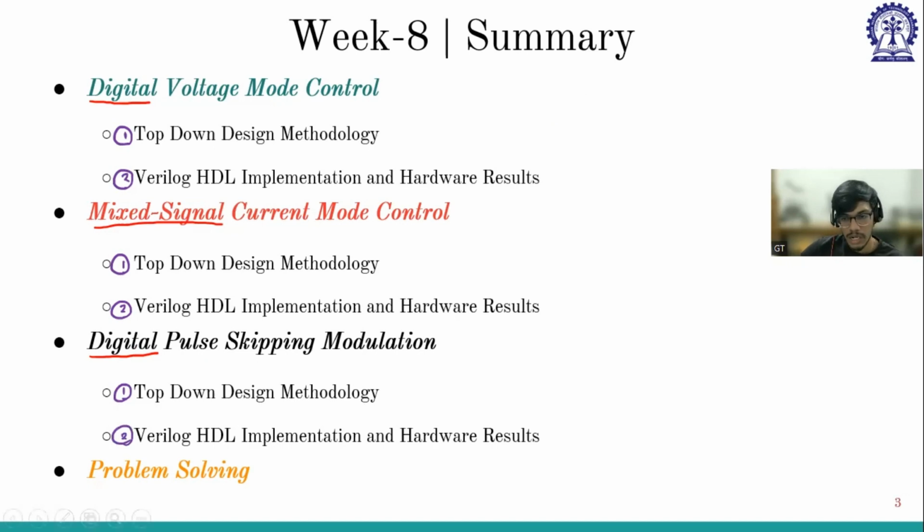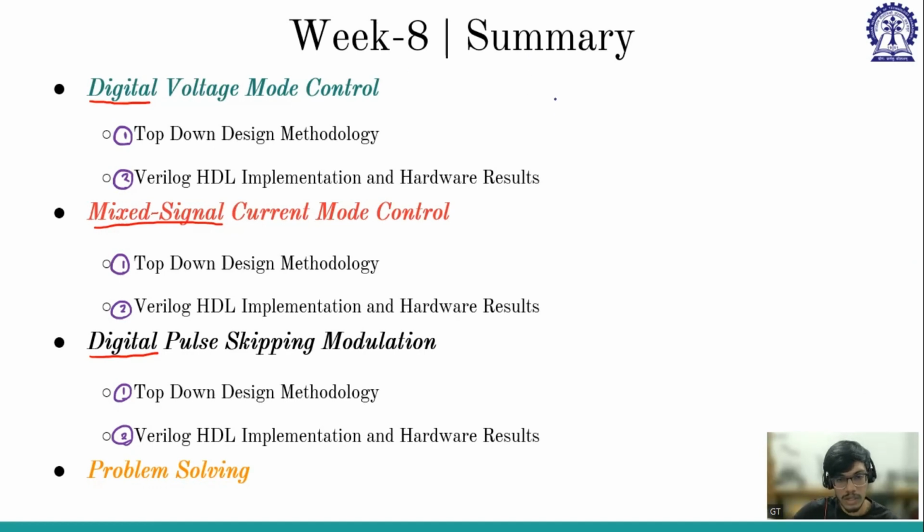If we consider digital voltage mode control, you are able to hear me, right? Yes, sir. In digital voltage mode control, there are a few sub-blocks. One is the main function. All of the control techniques have main functions, but they have sub-blocks. Here we have the clock generator, and then we have the digital PID, and then we have DPWM with Deadtime.